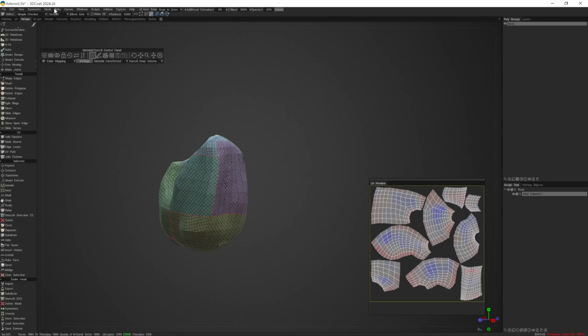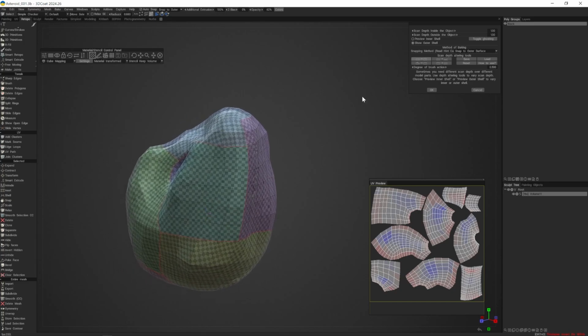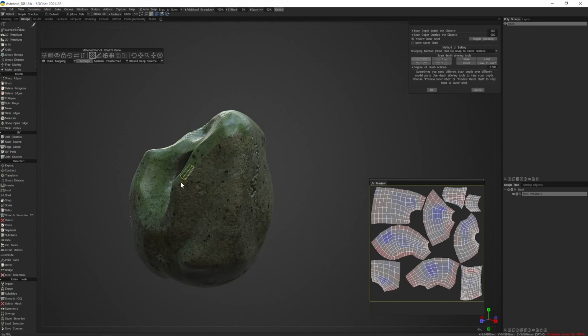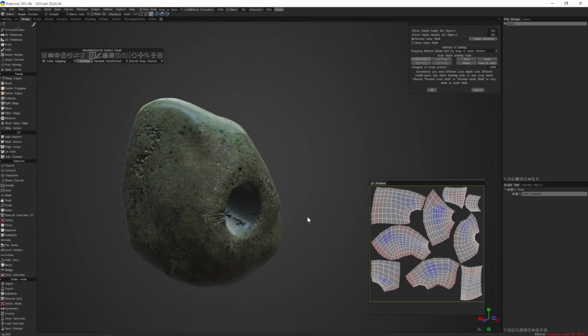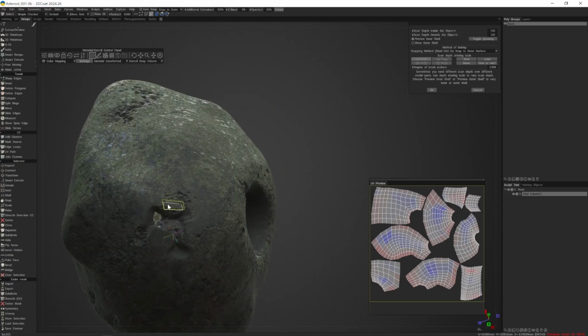So now I can go to bake up top here. There's an option here to bake. Let's save this incrementally. And we'll go to bake with normal map. Okay. And generally speaking, this is going to give us two bake cages, an inner cage and an outer cage. You can preview the inner shell and the outer shell here. We don't want the inner shell to be visible through our sculpt mesh. Okay, we generally want to make sure that none of the inner shell is poking through.